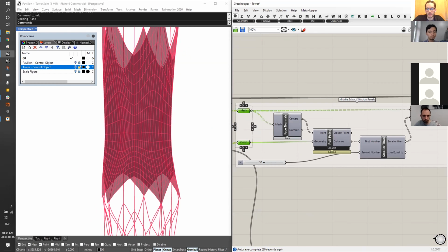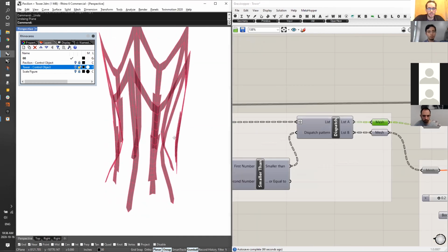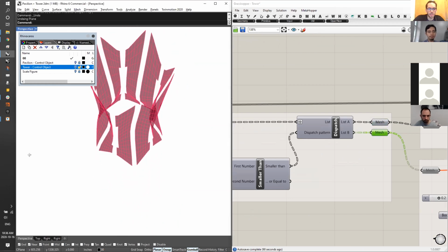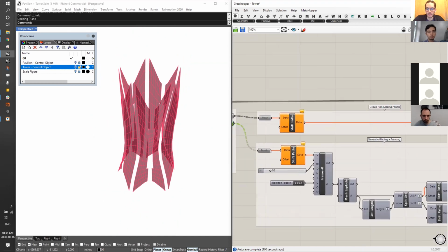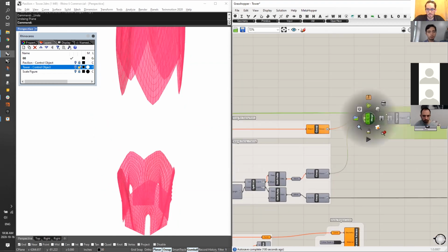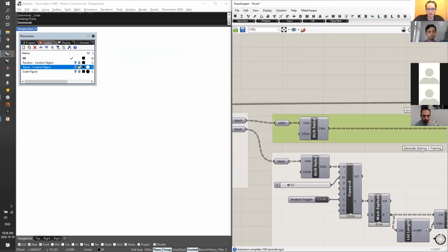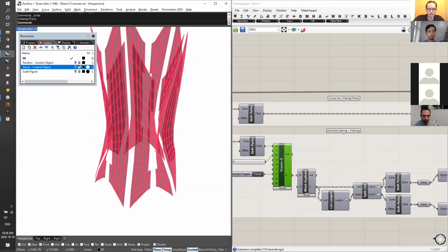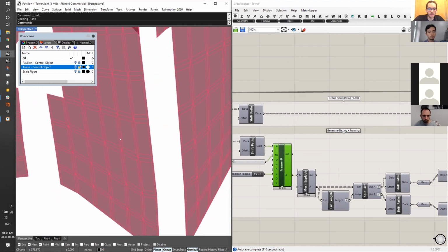We're checking the distance again between point and curve, and if you're smaller than some distance, in this case 50, then you're going to be kept. And if you're not, then you're going to be just parsed out. So in this case, these are going to be the glazing panels, or the panels that get the most amount of glazing. And then once we've isolated those two conditions, we can easily start to extract different properties from it. So this is just a quick way of creating framing.